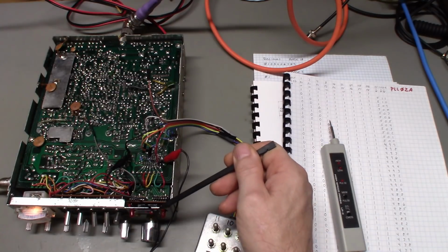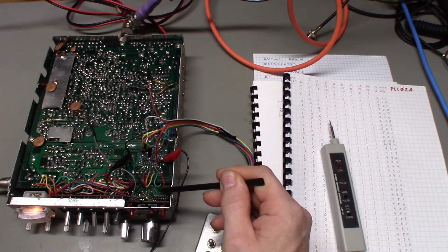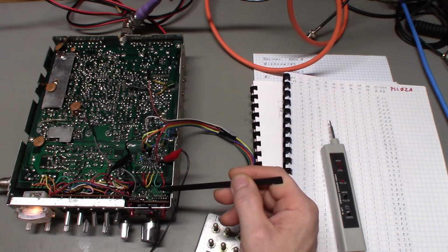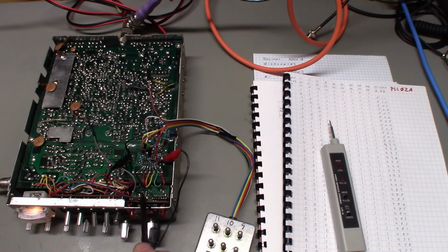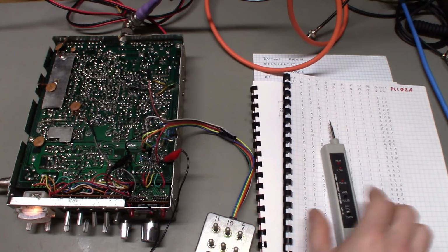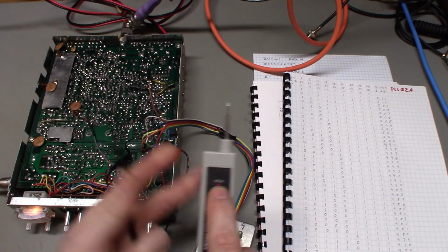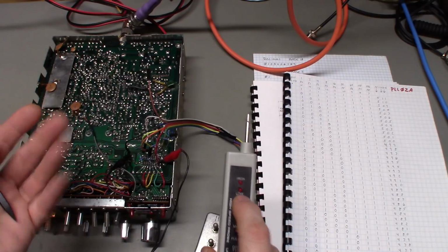All the traces were already cut to all of the pins, through all these wires, and that's what these wires are here. So the channel selector switch has a ground attached to it, and has a positive voltage source being sent to it, and then either voltage or ground is getting sent through these wires to the program pins. So that's all these are. That's it. Ground or voltage. That's all. And that's what the logic probe checks. High is a 1 or a voltage. Low is ground or 0.